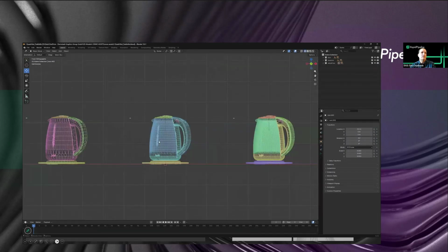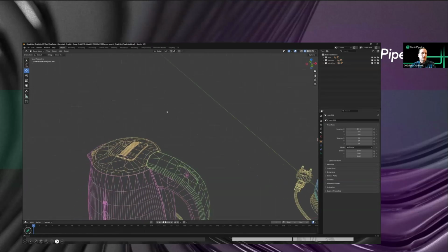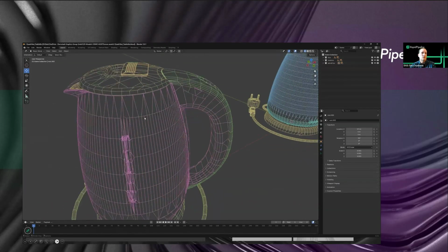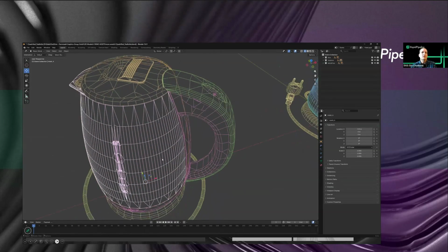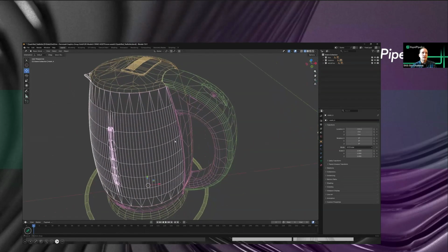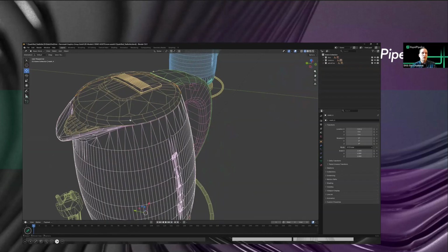So here I pre-converted this into quads, and based on the tessellations of the surfaces, it'll convert into quad meshes on export to USD. And so currently that's the feature, that you can convert to quads on export out to USD. And then these USDs are re-imported here into Blender to look at them.